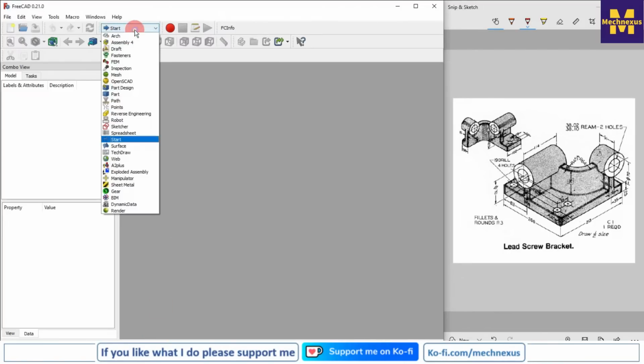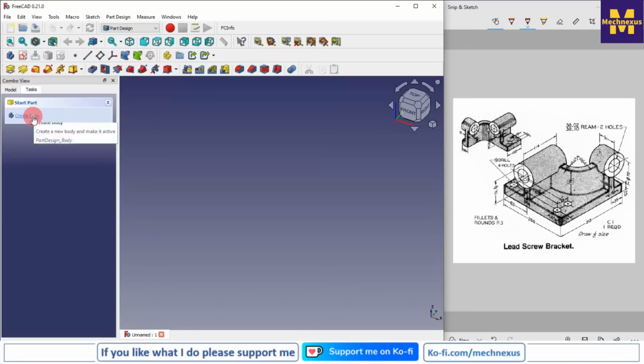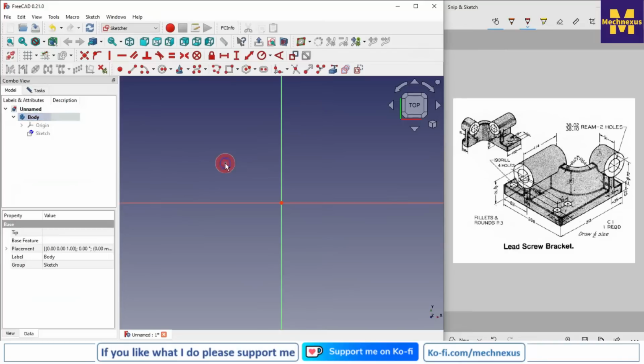So first I will switch to the Part Design, and then I create a new file and I create a body and then create a sketch. So here first we will model this base plate. For this I will select this top plane XY, and now we will read the dimension. So we can see that it is a 200 by 213.